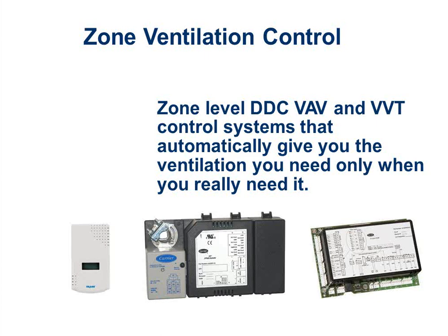So if you have an economizer and it's a relatively new economizer, the past 10, 12, 15 years, chances are it has a CO2 sensor input on it. It may be labeled IEQ, not CO2, but it does the same thing. So you can oftentimes retrofit a CO2 sensor onto an existing rooftop economizer and not have to do any work to the economizer or the unit itself. If it has a really old economizer, then either you should look at replacing the rooftop because it's a 20-year-old rooftop, or you might have to change the economizer controls. Or if they didn't have an economizer, you might have to add one.